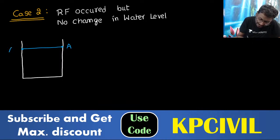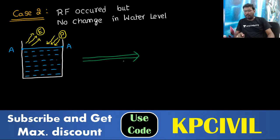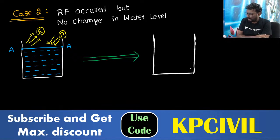Even on 0th day, even on 10th day, starting of experiment and ending of experiment. Evaporation takes place, escape of water from the pan takes place. At the same time there is an entry of water through precipitation. Both happen. Evaporation as well as precipitation, both occur. Then after T days, whenever your observation period is completed, what can we expect? Due to occurrence of rainfall, we expect that there may be rise of water level.